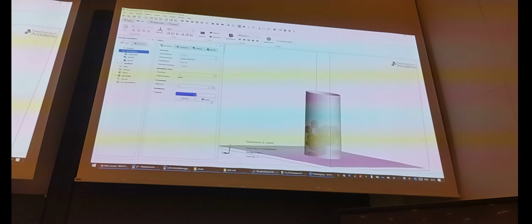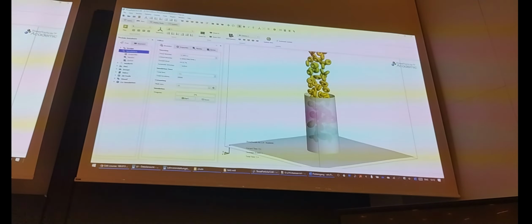Oh, unstable again. Yeah, you see that? At some point it suddenly gets unstable. And that's probably also one thing. With spheres, the critical time step is working quite well. As soon as you leave spheres towards donuts, toruses, like objects, boxes, cylinders, capsules, something like that, the critical time step gets a big problem. So this is too high, we'll go down even more.